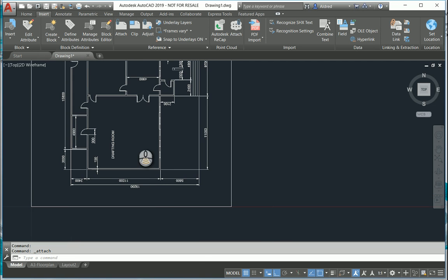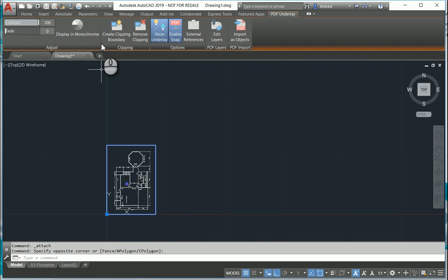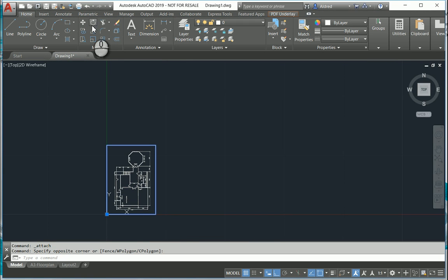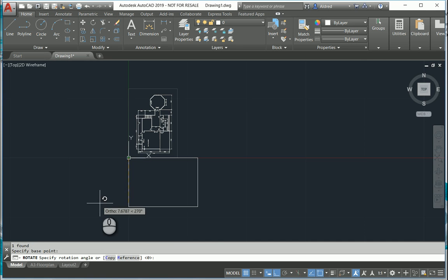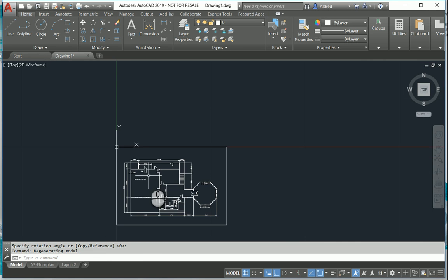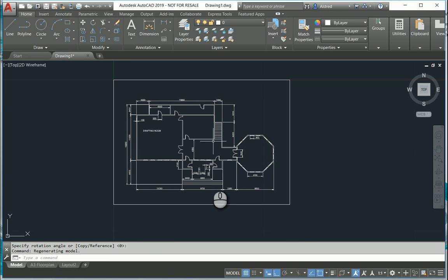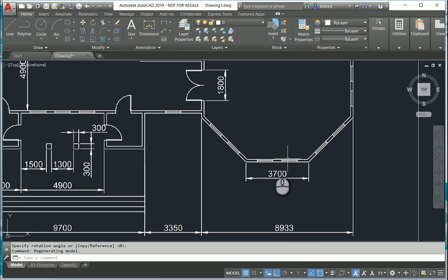And first of all, it's rotated at 90 degrees. So I can select it, and let's go to the rotate command and rotate it by 90 degrees over there. Okay, now I need to see exactly how big this is. So I'm going to test it using this 3,700 millimeter dimension reference. If I go to my utilities, measure, and I measure this, you'll see that it's only referencing 1.0219. Now that's a bit of a problem because it's actually supposed to be 3,700.